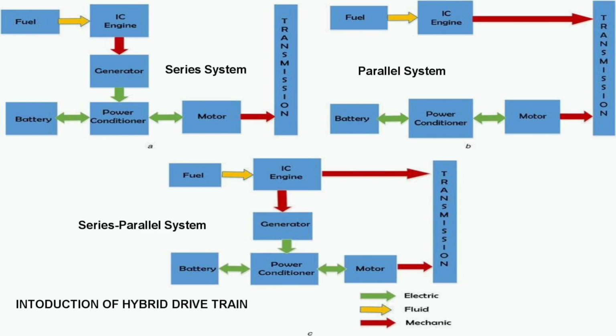The drawbacks of parallel hybrid drivetrains are the mechanical coupling between the engine and the driven wheels. Thus, the engine operating points cannot be fixed in a narrow speed region. The mechanical configuration and the control strategy are complex compared to the series hybrid drivetrain. Due to its compact characteristics, small vehicles use parallel configuration. Most passenger vehicles employ this configuration.